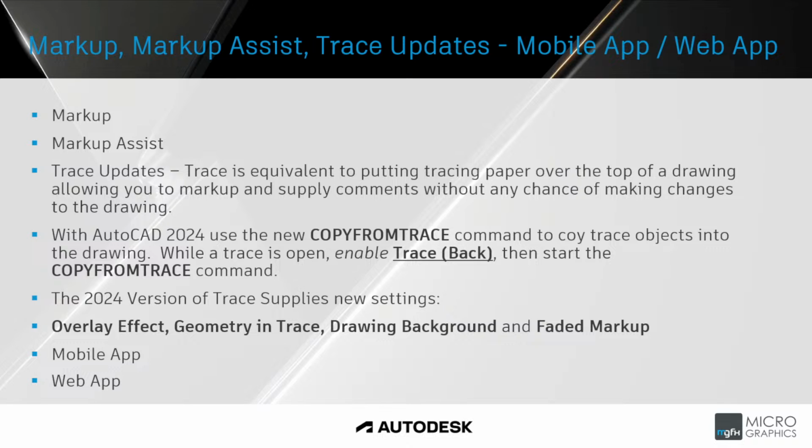With AutoCAD 2024, use the new Copy From Trace command to copy trace objects into the drawing. While a trace is open, enable Trace Back, then start the Copy From Trace command. The 2024 version of Trace applies new settings, such as Overlay Effect, Geometry in Trace, Drawing Background, and Faded Markup.